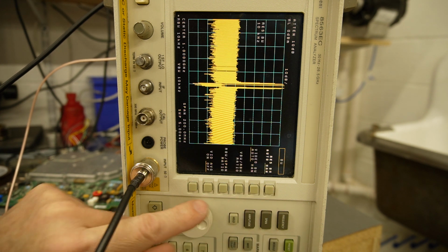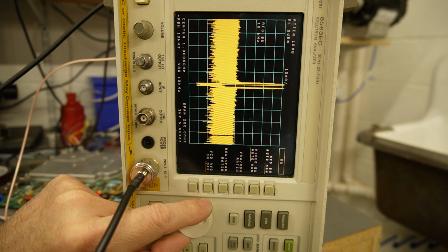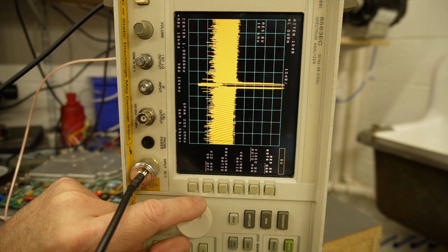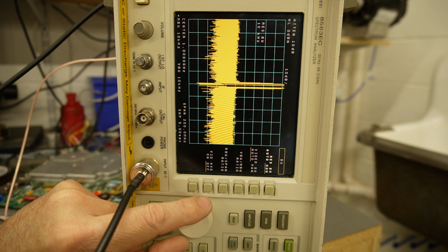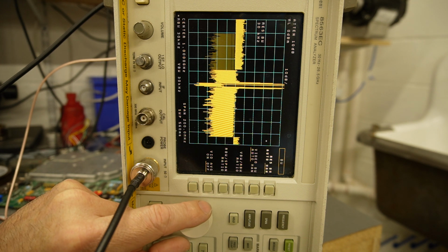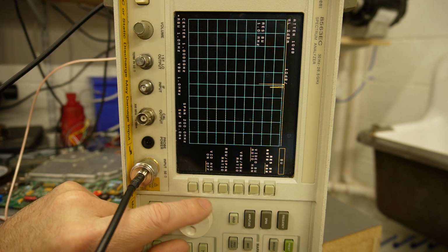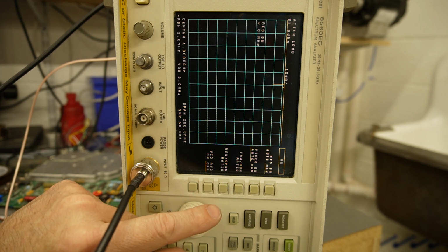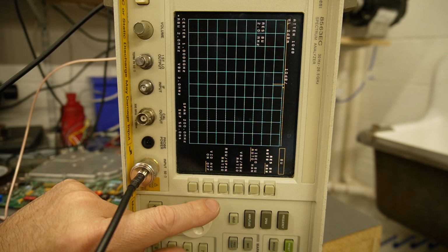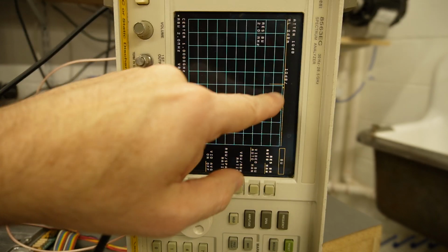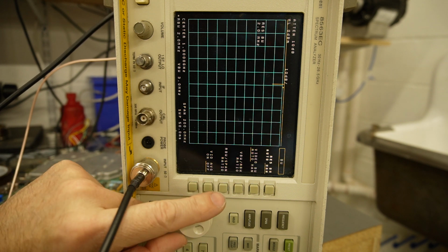And let's change the resolution bandwidth a little lower. Now it's a 5-second sweep on that. That's a 10 kilohertz RBW, resolution bandwidth. So there's a 30 kilohertz, 100, and you can see that noise floor goes up, or that base value goes up. And if we go up high enough, you'll see almost all. Now that's a 2 megahertz, which seems to be the max resolution bandwidth, which is kind of like the minimum number of points taken. And you can see there's just a little line appearing from there.